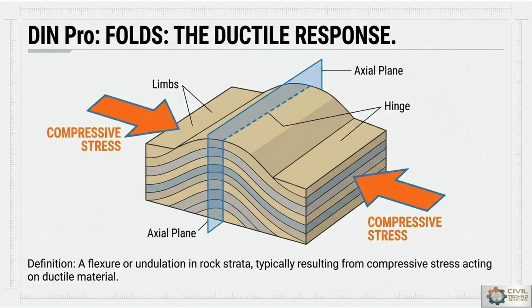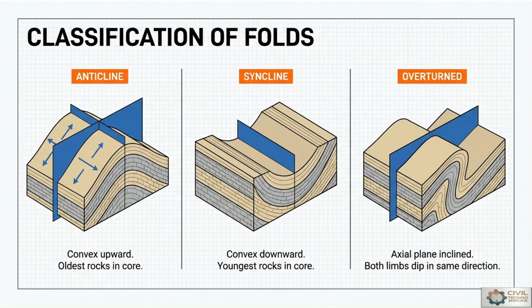Folds are bends or curved structures that develop in the rock layers due to compressive tectonic forces. Unlike brittle faulting, which represents the displacement of rock masses, folding is ductile deformation. Fold structures influence groundwater flow, slope orientation, and underground excavation behavior. Therefore, fold interpretation is important for geological mapping and civil engineering site investigations.